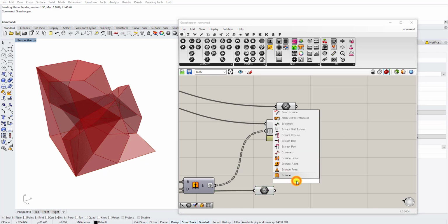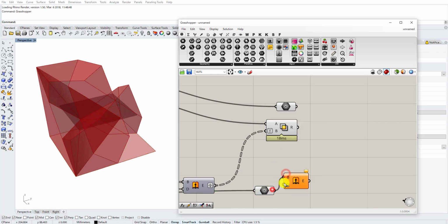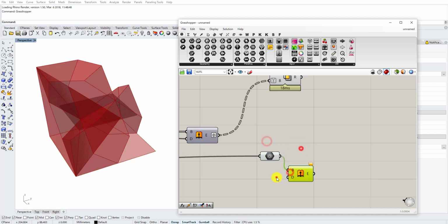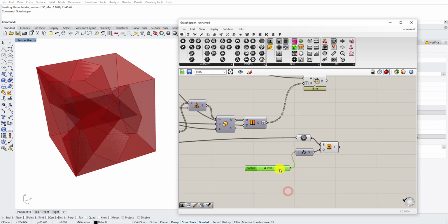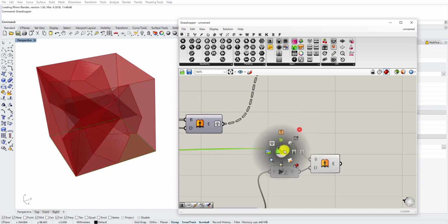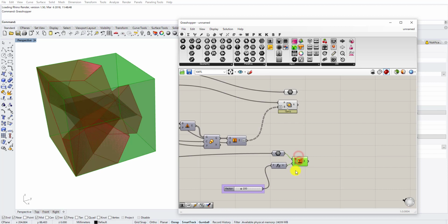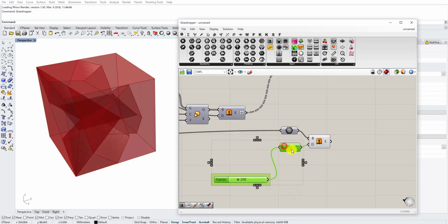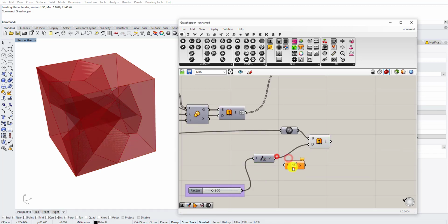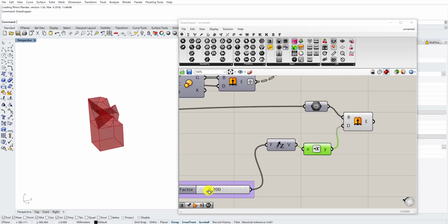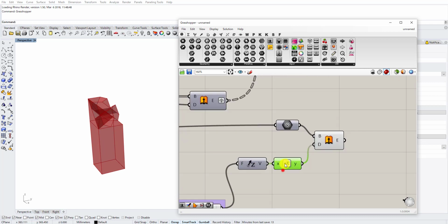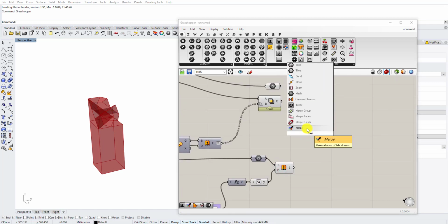And maybe I would want to extrude this in the -C direction for some amount, something like 200 could be parameterized for this one. Okay, right, and yeah, I need a minus here, negative here. Okay, like this. Now let's merge this together.